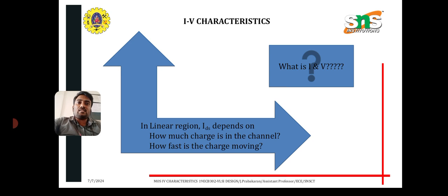Current-voltage characteristics: a graphical plot of IDS versus VDS for various VGS, which means gate source voltage. Carrier velocity and mobility: speed at which charge carriers move through the semiconductor material under the influence of an electric field. Activity refers to the state of the transistor based on the applied voltage.